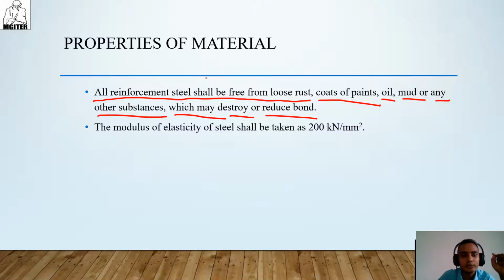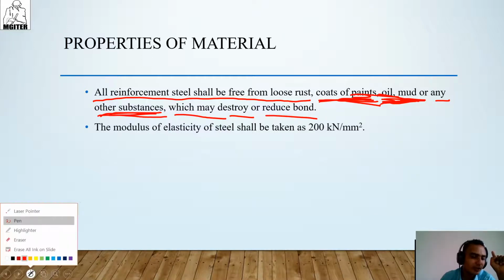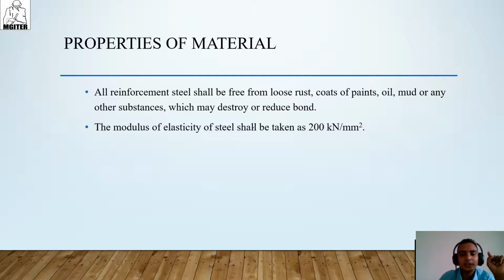That means if reinforcement steel has a coat of paint or oil or any other substances, these are the causes that affect the bonding between reinforcement steel and concrete.